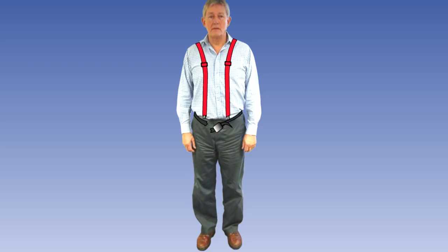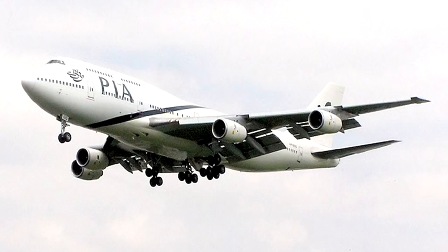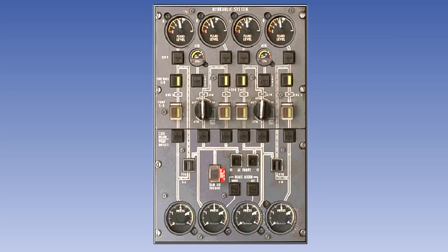In order to achieve this, the fail-safe design concept uses one or more design principles or techniques to ensure a safe design. Redundancy and backup systems are used to enable continued function after failure of one or more systems. A good example of this is the use of multiple engines. Systems and components are isolated and segregated so that failure of one does not cause failure of another. For instance, aeroplanes are designed with multiple independent hydraulic systems, with no transfer of fluid between them.